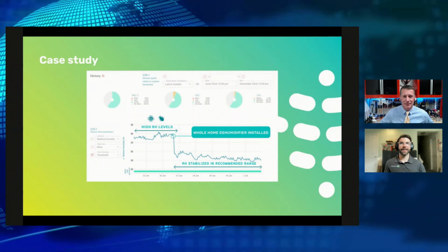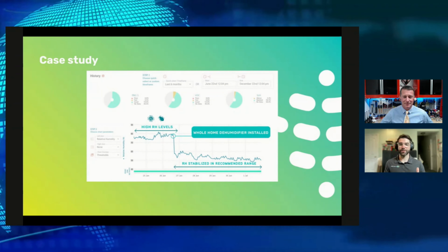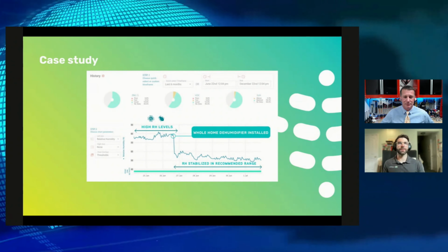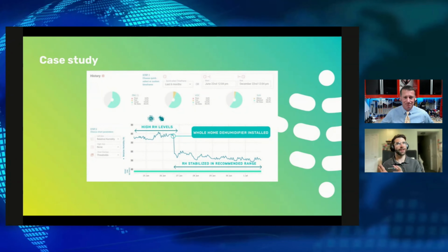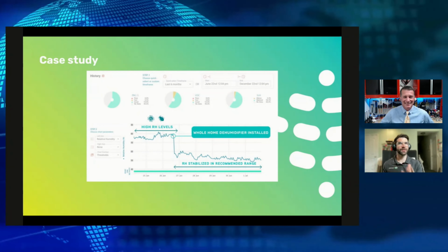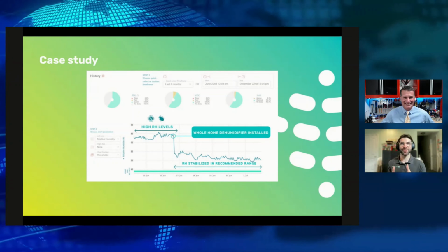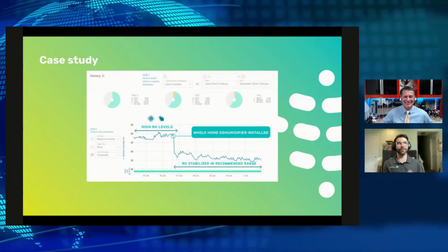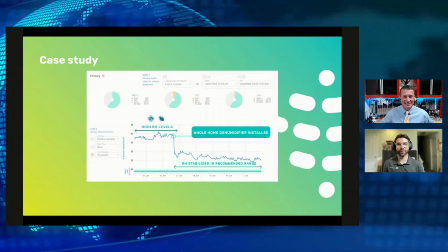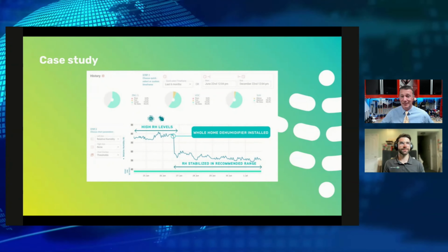Yeah, I've always thought there's an opportunity to take the CFM a system can move and multiply it to get an equivalent clean air delivery rate, which is the metric these air filters use, and say, this is equivalent to three or four of those room air purifiers. Absolutely. Very good comparison.